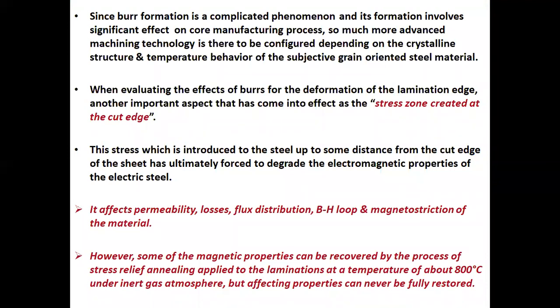Since burr formation is a complicated phenomenon and its formation has a significant effect on the core manufacturing process, much more advanced machining technology is to be configured depending on the crystalline structure and temperature behavior of the subject grain-oriented steel material. When evaluating the effects of burrs on the formation of the lamination edge, another important aspect that comes into effect is the stress zone created at the cut edge.